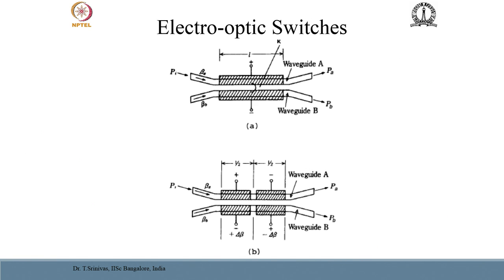So, this is another example of electro-optic switches that we have already seen. There are a lot of configurations that we can think of. Typically I would like to highlight the second portion where there is a delta beta coupler. You can choose the voltages across these couplers to change the properties and tune according to the requirement, and you can also compensate for the fabrication tolerances and the minor electrical voltage variations and get a very stable modulated output by such a configuration.